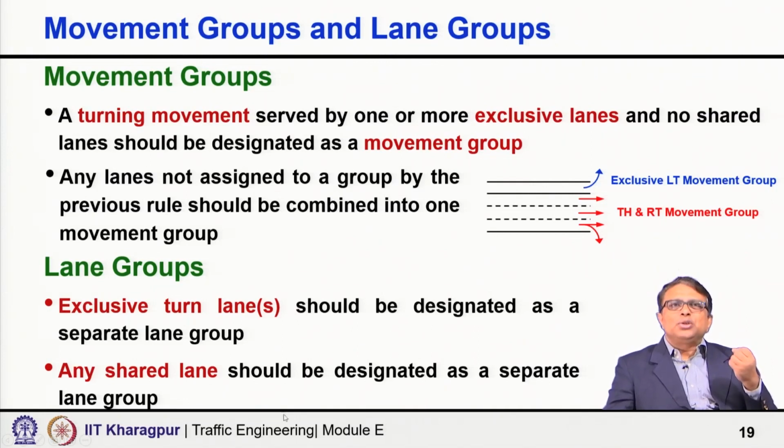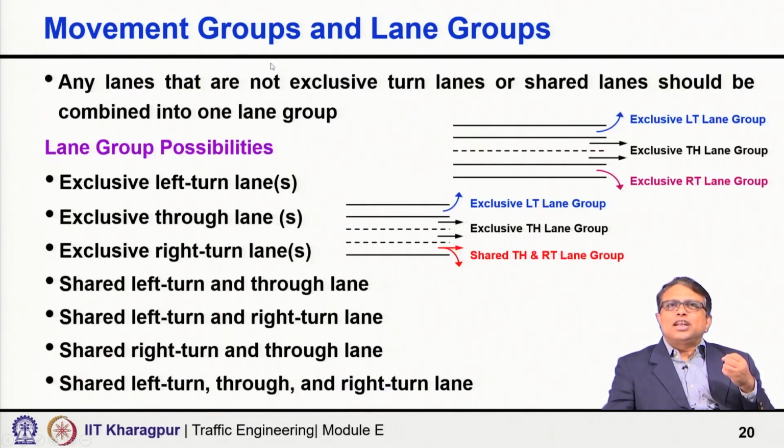Now, coming to lane groups, an exclusive turn lane should be designated as a separate lane group, and any shared lane should be designated as a separate lane group, and any lanes that are not exclusive right turn lanes or shared lanes should be combined into one lane group.